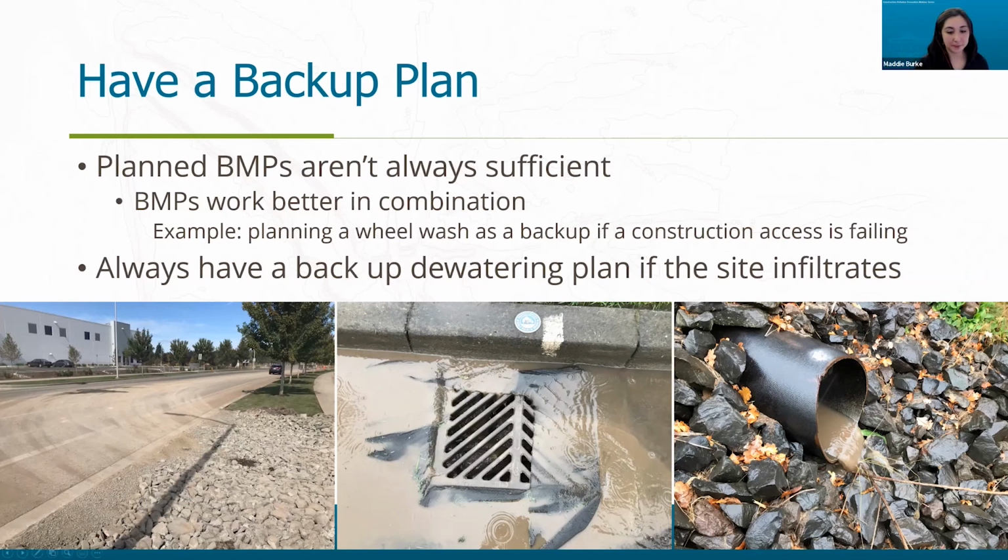So the site below, they did all the BMPs according to their plan, and they had tried really hard to keep sediment on site. So in this first picture, when I showed up, you can see a lot of sediment on the road. They had a street sweeper running during this time to try and clean it, and there's still so much dirt on the road. They had a 200-foot construction access, which is much longer than standard, to try and control this. So, they were putting in the effort.